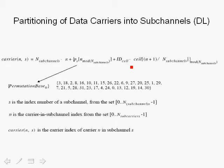There'll be a low probability of a hit in that case. So by using a different ID cell for different cells, the permutation is such that the subchannels within adjacent cells don't have coincident carriers, and there's less chance of interference between the two. In other words, the probability of using the same physical subcarriers in adjacent cells and sectors is reduced.